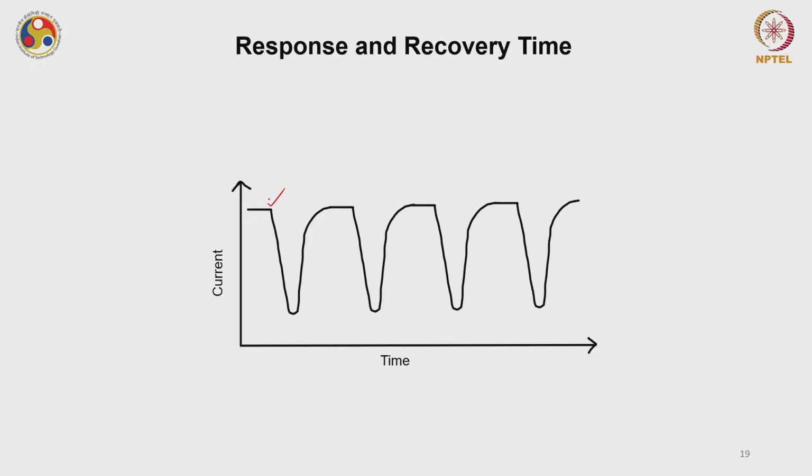At this particular position, I have applied the analyte. Or at this particular point, my sensor is exposed to some analyte. Now, it has reached, say, this is the maximum value. Response time is defined as the time it takes to rise from 10% of this value to 90% of the maximum value. This time frame is known as response time.